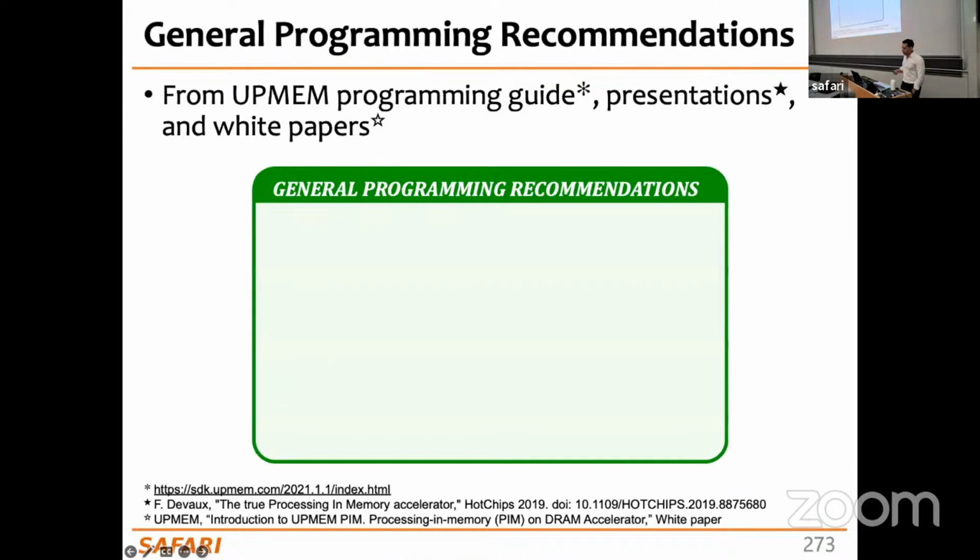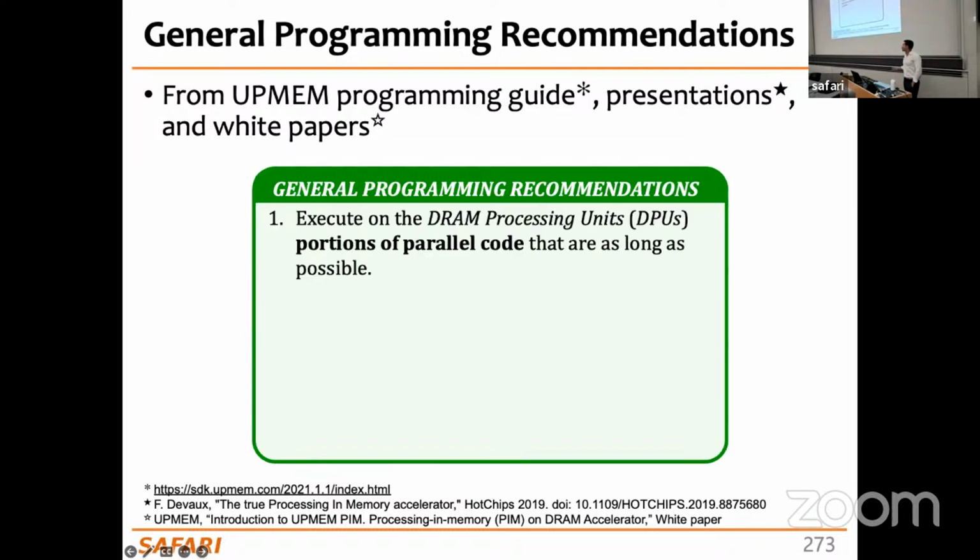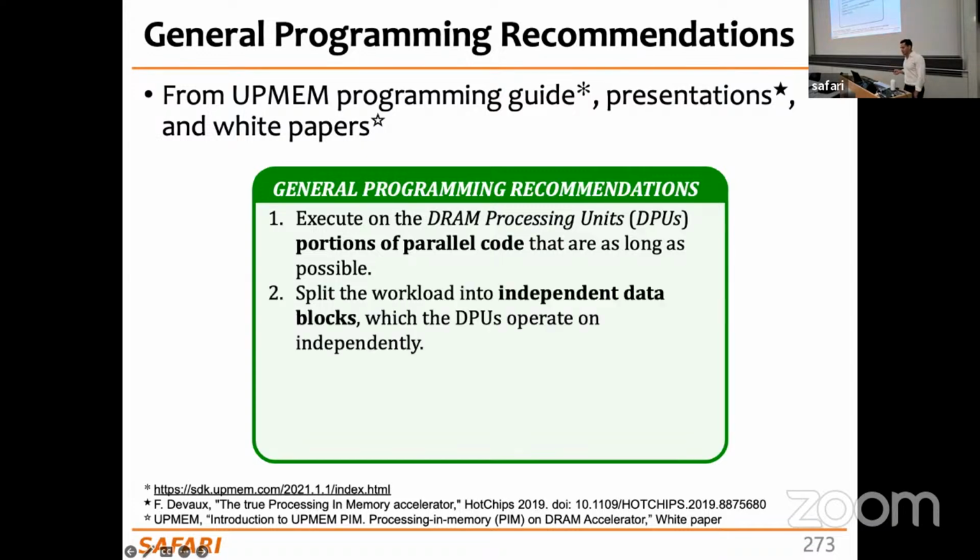So overall, some programming recommendations that we learned over time programming this UPMEM system: if you take your application kernel, you have your input data and your tests that you need to execute, you want to parallelize the tasks in a way that you can run parallel portions of this code in the DPU as long as possible, so you fully utilize them.